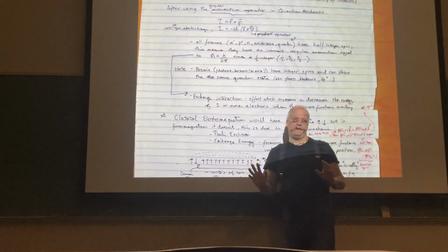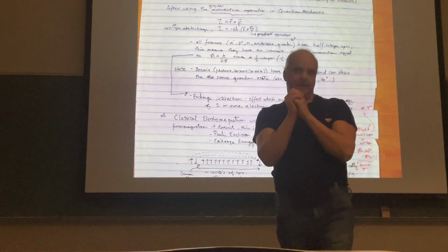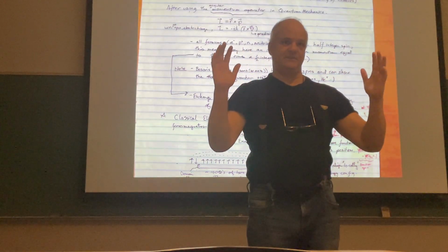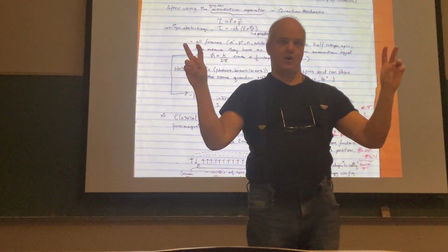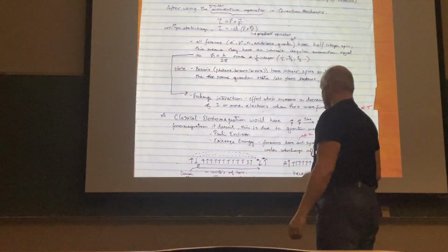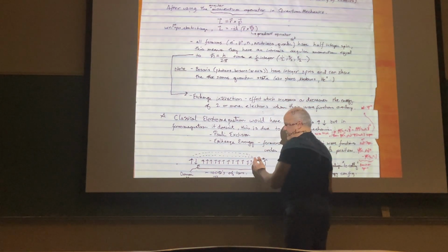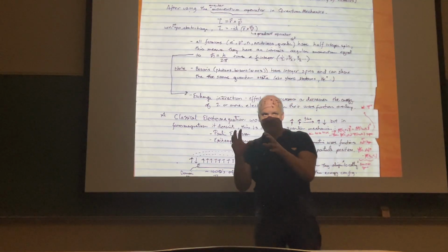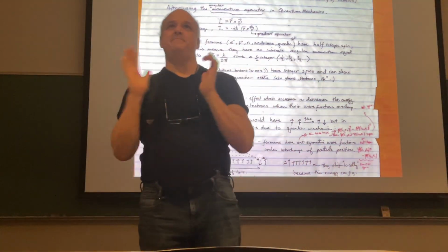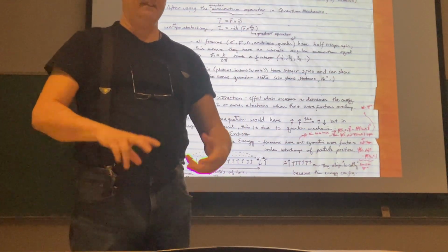So the thing about magnetism in these domains, you've heard the word domains, is that a bunch of these domains can add together in these weird materials and be up to a certain size, and then suddenly a wall occurs and you get a flip to something else, and this is a domain wall. And so you can get up to 1,000 of these little ions making this little domain. The thing that magnetic memory was trying to do, and still trying to do, is to make those domains smaller, but you can't get beyond a certain size. And if you do, they become unstable. So you can start having bit flipping.